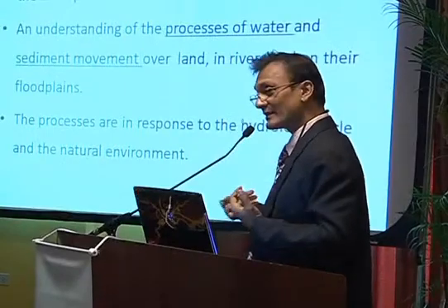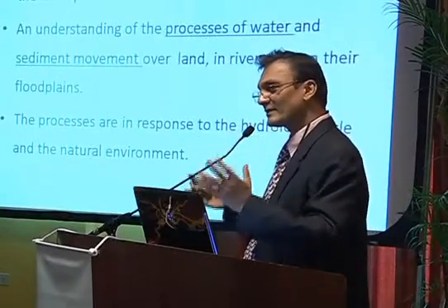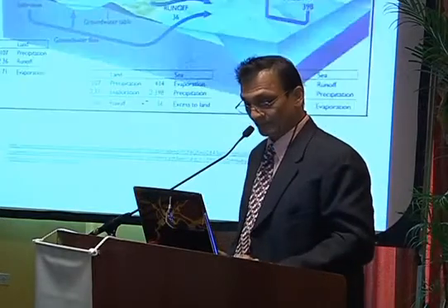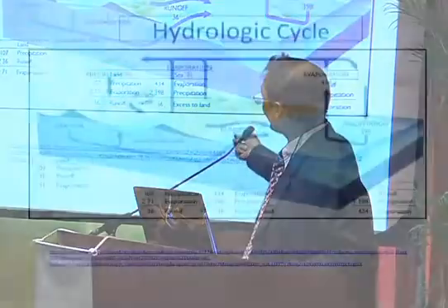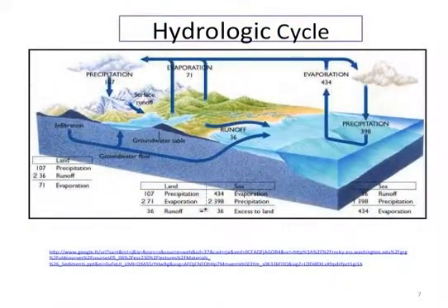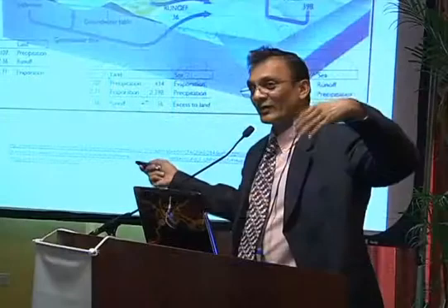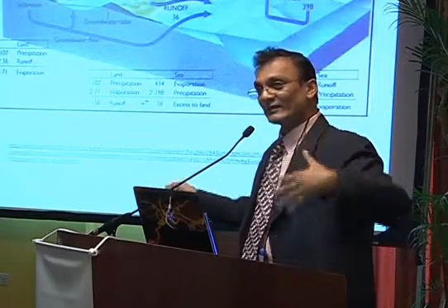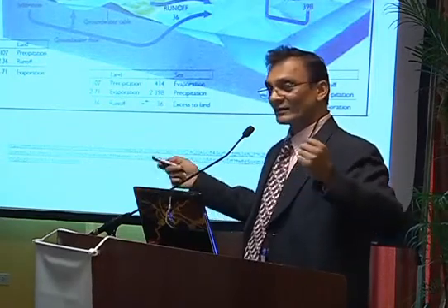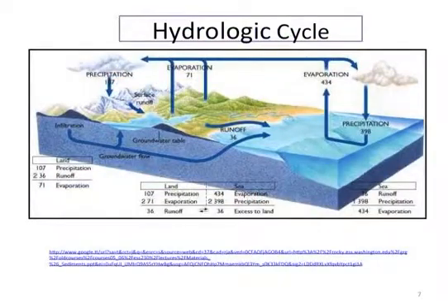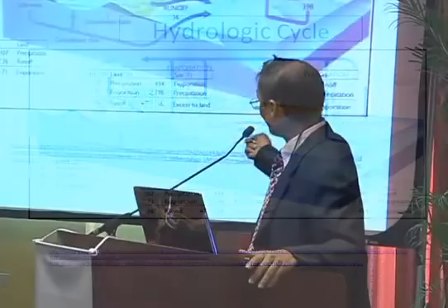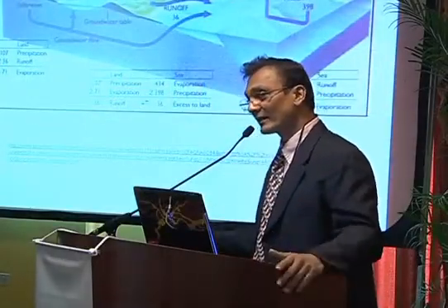So the sediment movement is in response to the hydrologic cycle. And to review what that is: evaporation at the surface, condensation, precipitation, and runoff. Now on the steep slopes of the hill, weathered material will be easily transported. There's a lot of water energy. So it transports volumetrically a lot of sediment and also large sizes. However, when it encounters low slopes or pools, you will have sedimentation occurring, and the sediment moves with the flow, and when it reaches the coast, you then get beaches and wetlands being formed.